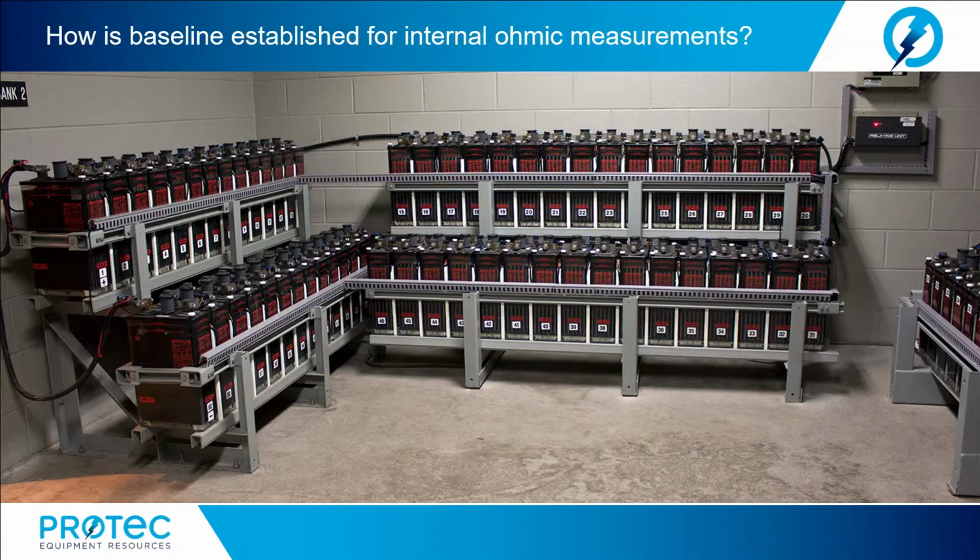Now, although many manufacturers may have provided baseline values, which will allow trending of the internal ohmic measurements over the remaining life of a station battery, these baselines are not the actual cell or unit measurements for the battery being trended. It is important to have a baseline tailored to the station battery to more accurately use the tool of ohmic measurement trending. That more customized baseline can only be created by establishing a baseline for each of the cells at the time of installation of the station battery.